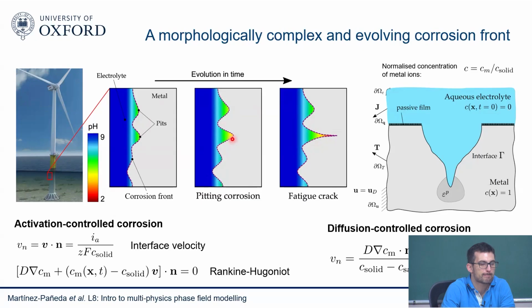Okay. So the governing equations and what you assume for a normal sample under electrolyte of sufficient depth, versus this one where oxygen exchange is much more rapid because your film thickness is only so much. You're saying this is because you have these conditions with water and oxygen because you get waves, or is that what you're thinking? Or your electrolyte, the water droplet through which this atmospheric corrosion happens, is very small.